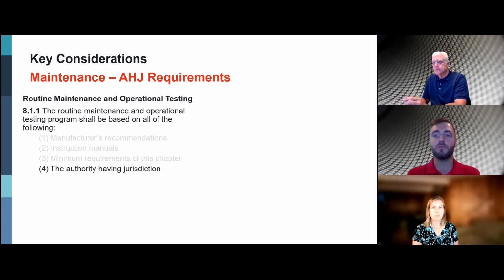Another example would be if a healthcare facility were to have a Tier 4 certified product to meet the needs of EPA stationary non-emergency regulations. There exist maintenance requirements for the aftertreatment on those products that must be maintained. This may include key maintenance points of the diesel particulate filter, or the DPF, and components around the storage and delivery of DEF, or diesel exhaust fluid, in the system.